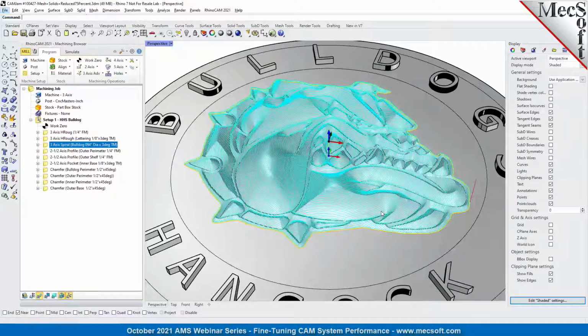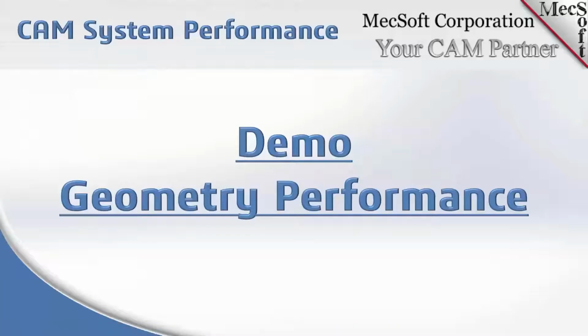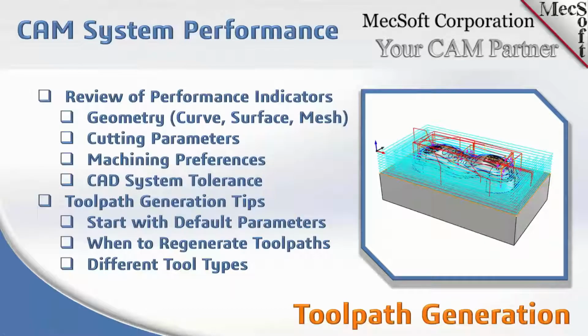Okay, and actually, there are a lot of users that use mesh files that are prismatic, like mold bases and things like that. If you're working with a prismatic part, there's no need to have 50,000 triangles. Okay, if it's just straight edges, straight walls, you can reduce that mesh 99%. So let's go back into the presentation. So that was the geometry performance part. Now we're going to look at toolpath generation.